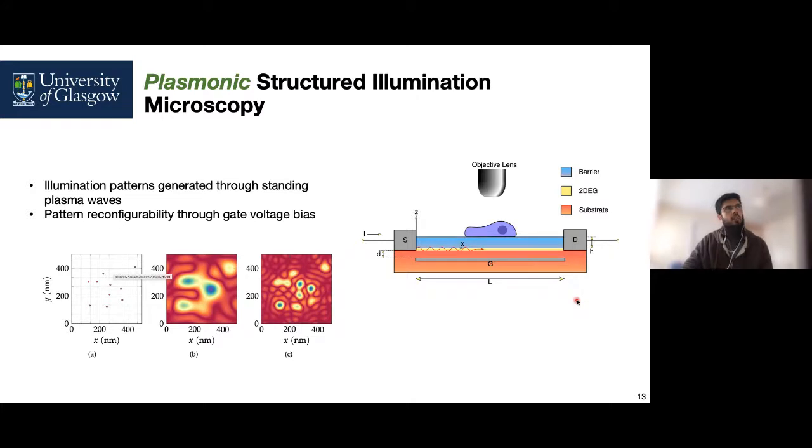Moreover, the plasmonics that we have observed, especially at the terahertz frequency, the surface plasmons, are much more sub-wavelength scale than the optical frequency surface plasmons. So this enables us to construct imaging techniques that provide much higher resolutions, going much beyond the diffraction limit.